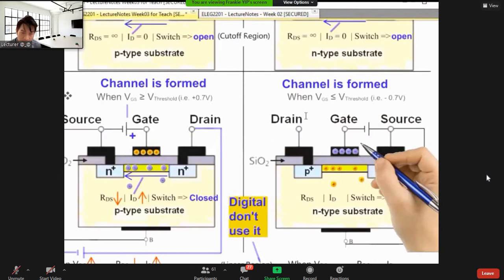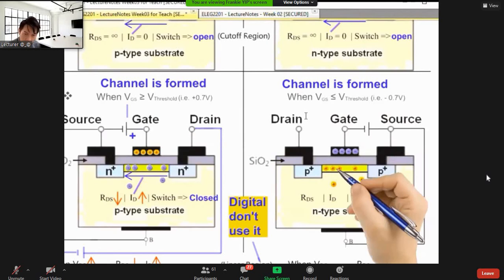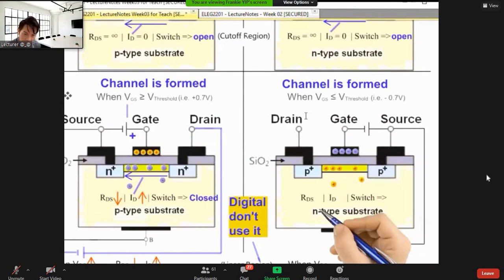So once again, let's see here. When the VGS is much smaller than or equal to negative 0.7, it attracts more holes over here, okay? For simplicity, you treat it to be positive charge, but it's not the case. You repel the electron, think about this. So the P channel is formed.